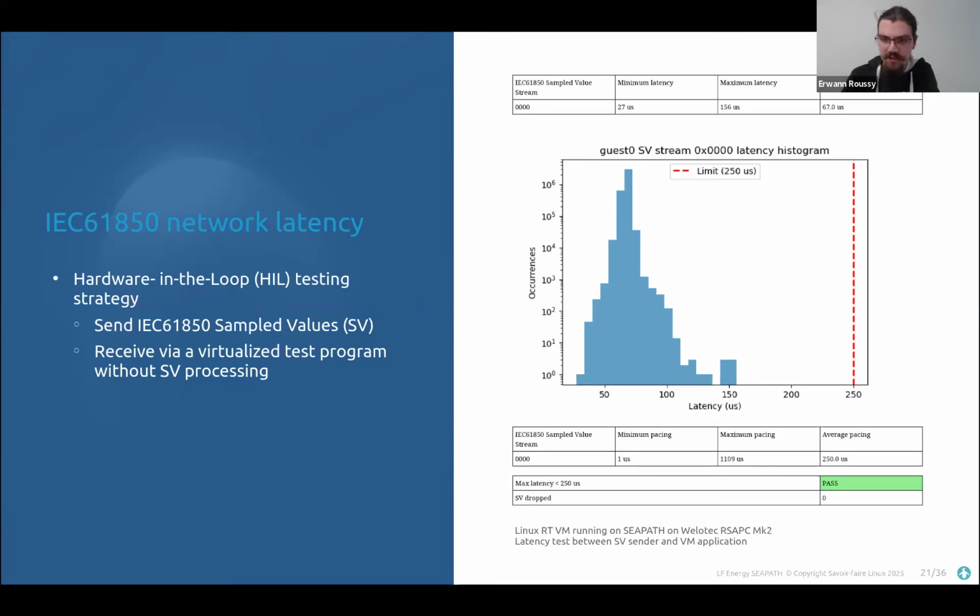The airspace project is an industrial use case of SEAPATH. This one is very interesting because it's production usage of SEAPATH in a small primary substation, for non-critical applications for now. The protection applications are still running on hardware boxes, but SEAPATH is running all the non-critical stuff in production. And regarding the protection algorithm, it's the Viper R&D project, which is evaluated by RTE with ABB protection and Schneider Electric also developing a protection.